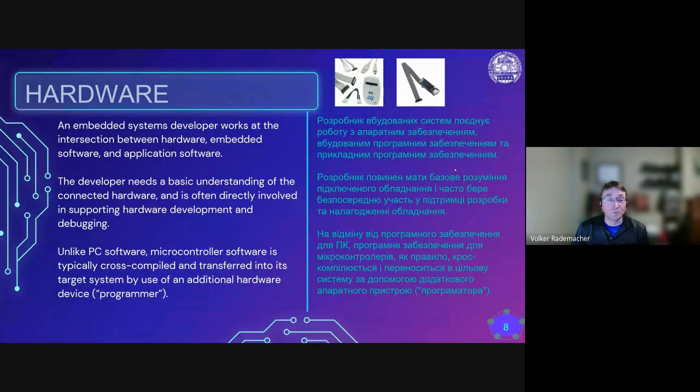Sometimes you will be the first one to see these problems when your firmware is showing sporadic errors that are being caused by components that are out of tolerance or insufficiently specified. In particular, for example, ceramic capacitors are terrible at this in terms of tolerances, and also transistor gain at the temperature extremes.